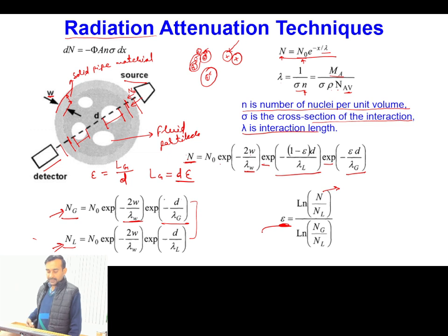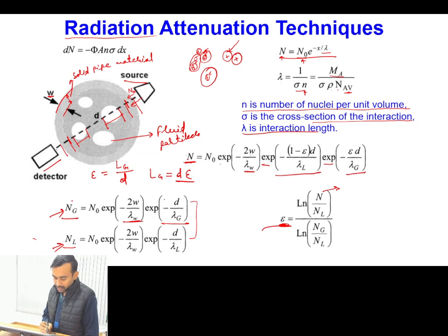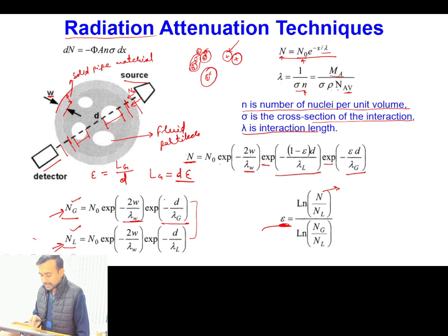It means that if you have an arrangement which can supply the signal and one which can detect the signal for a pipe material, and once you have calibrated it with pure gas and pure liquid flow, then for any arbitrary signal n obtained at the detector, we will be able to predict the value of the one dimensional void fraction. All are clear with this point?